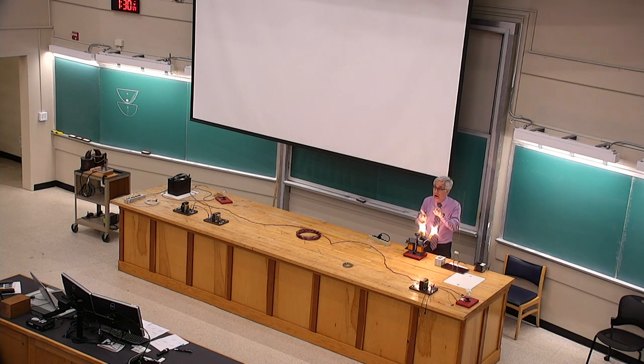Once I turn it on, the current that's now flowing in that secondary coil is important. It has its own magnetism, and because that current is changing with time, it has its own electric field. And that electric field talks back to the first coil and causes it to consume more electric power. So as you consume more electric power in the secondary circuit by turning on light bulbs, the primary circuit requests more electric power from the power company. It all works out self-consistently.